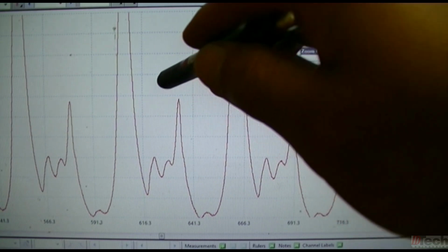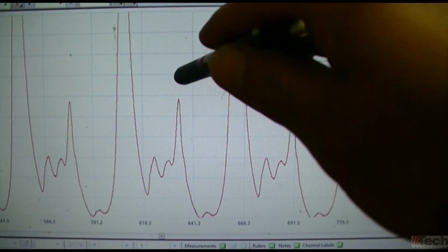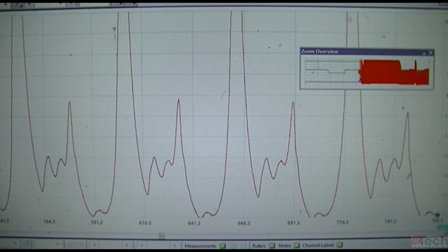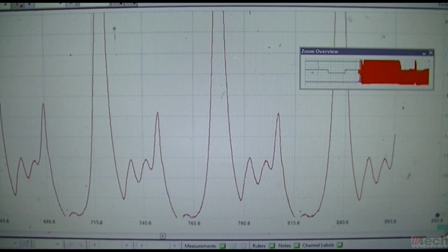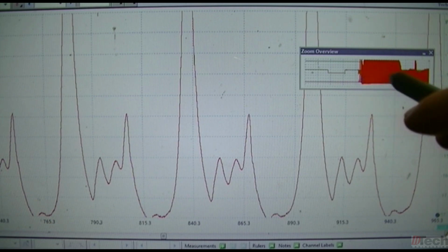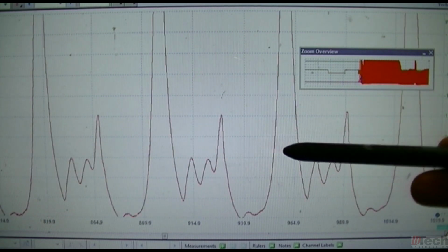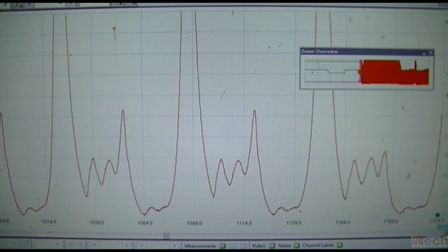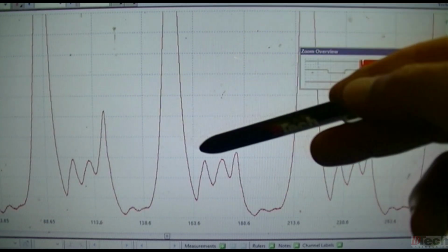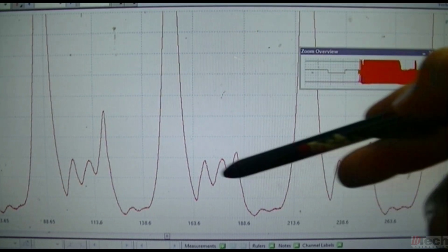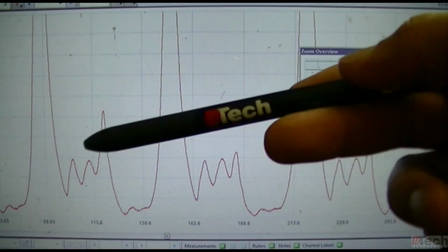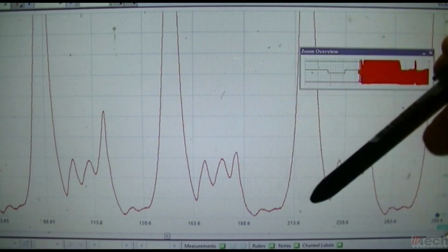But we're not really wanting to look at numbers right now. I want you to look and see what this looks like as we travel through the idle portion. And so we're scrolling all through the capture, and just keep in mind this point right there. From that cycle to this cycle, that point drops out. Right there, we're seeing phasing occurring.